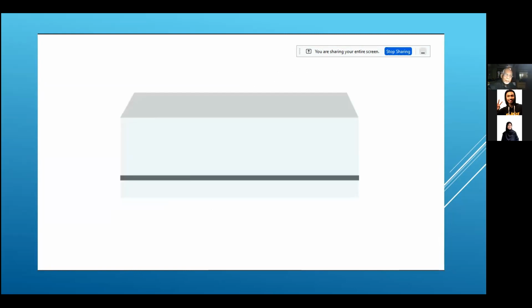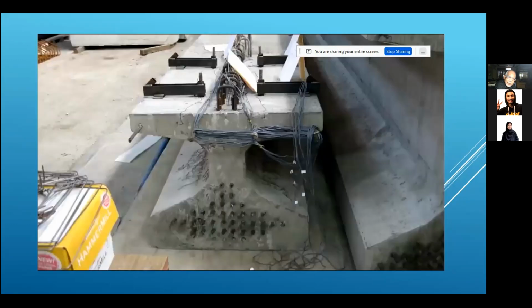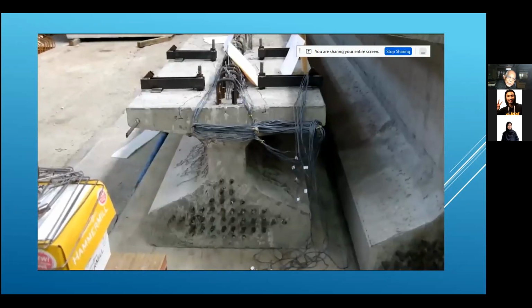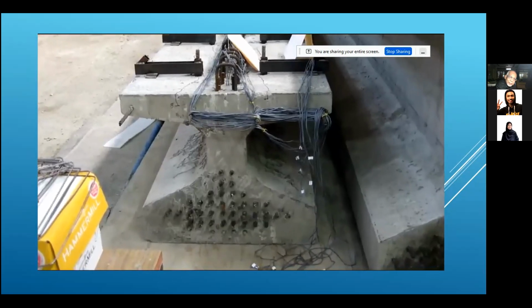One way to do this is to put tension on the steel reinforcement tendons as the concrete is cast. Once the concrete cures, the tension will remain inside, transferring a compressive stress to the concrete through friction with the reinforcement. Most concrete bridge beams are pre-stressed in this way. Check out all that reinforcement at the bottom of this beam.